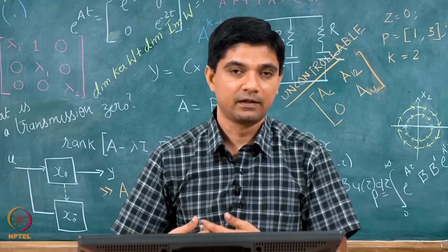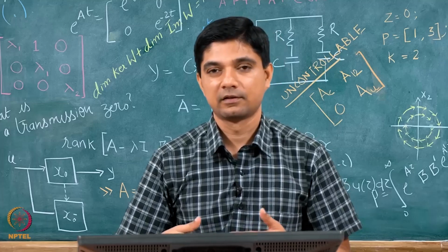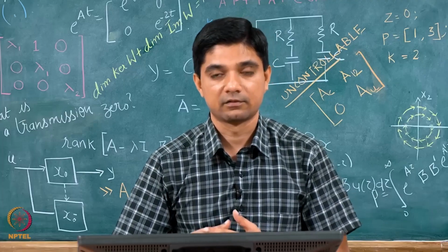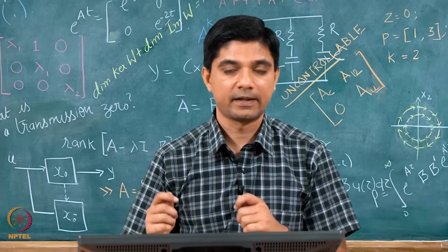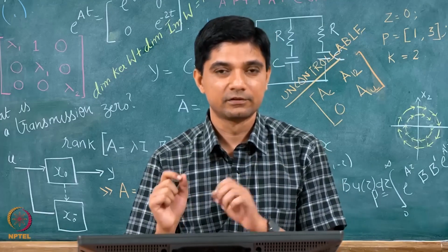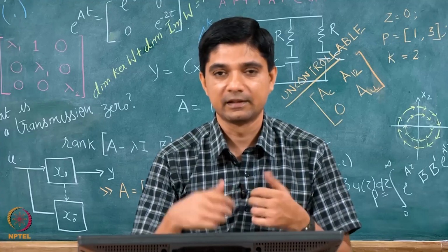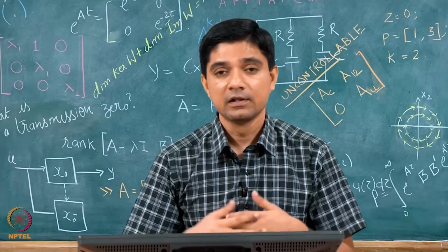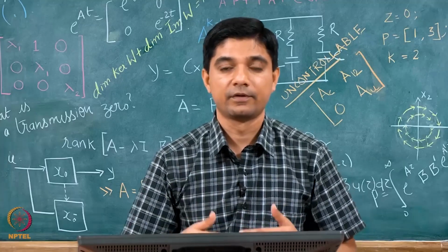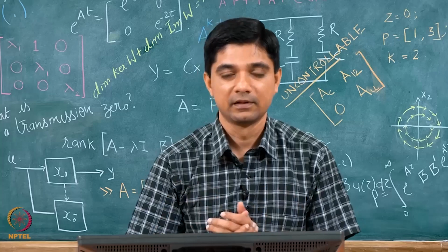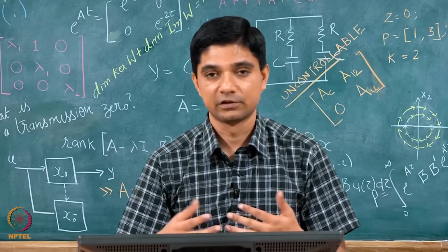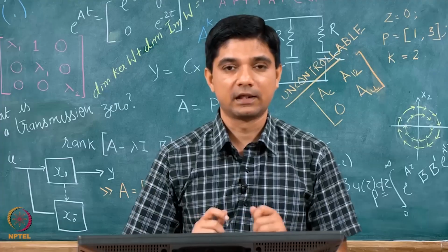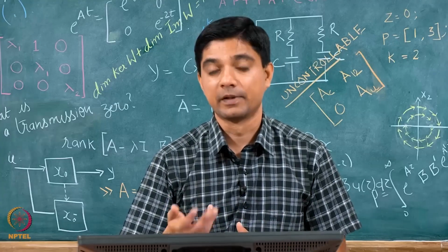So, towards the end of the course in week 12, we will spend a lot of time looking at computational aspects of these kind of inequalities, which are also called linear matrix inequalities. We will look at all these inequalities which we see in terms of Lyapunov stability, A transpose P plus P A being less than 0, and so on. So, we will spend some time actually finding out ways to solve these. I will also maybe introduce you to some MATLAB packages which solve these kind of equations. So, if you are confused about what to do with these equations, just hold on, I will give you some very easy methods to check numerically how these work.